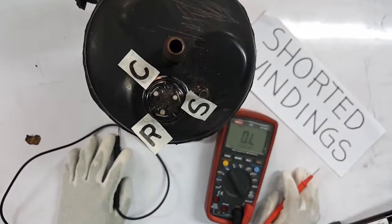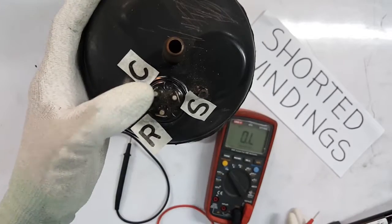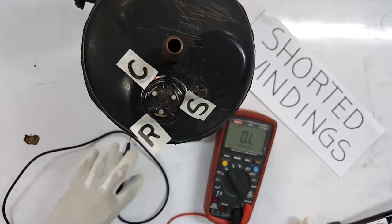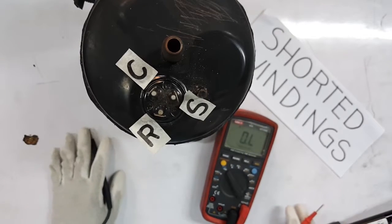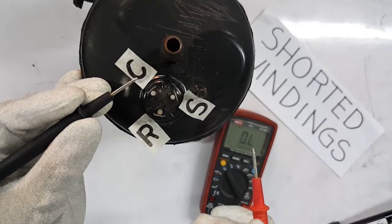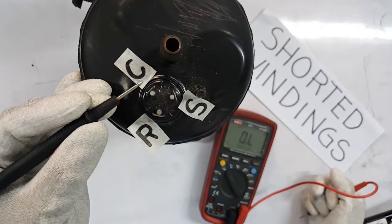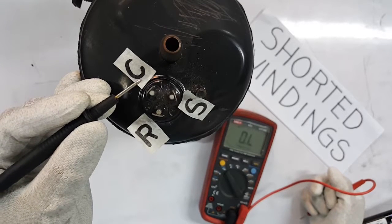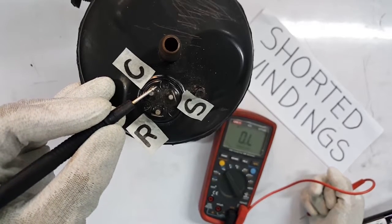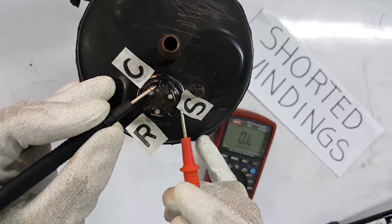Example of our shorted windings. So this is another set of compressor. Again, we have common, running, and starting, using the DMM or digital multimeter selected at resistance. So let's check. We are expecting, based on the shorted windings, that the resistance is lower than that of a regular good running compressor.